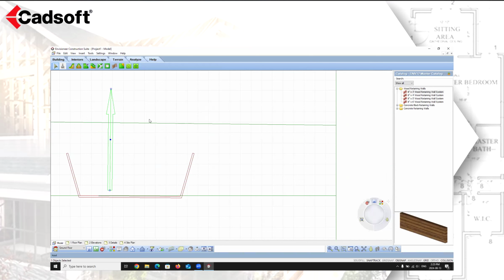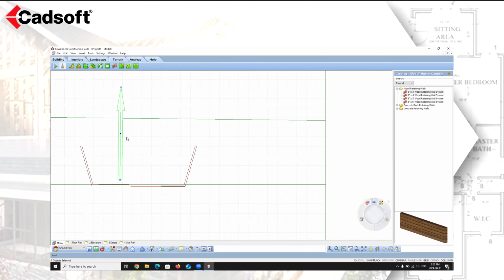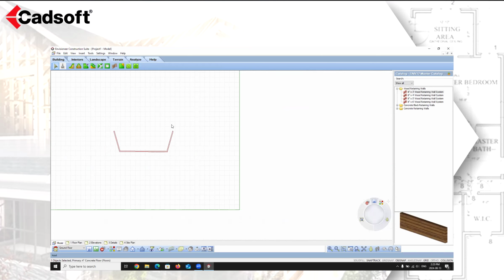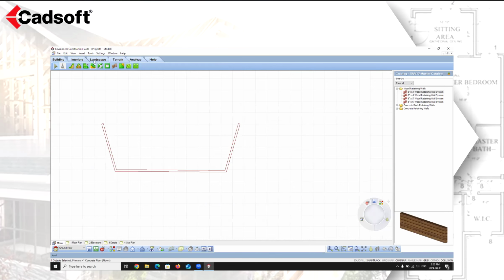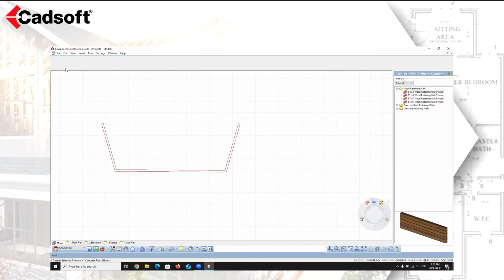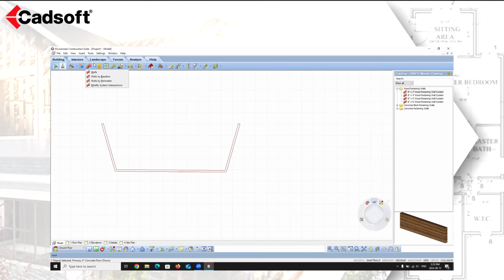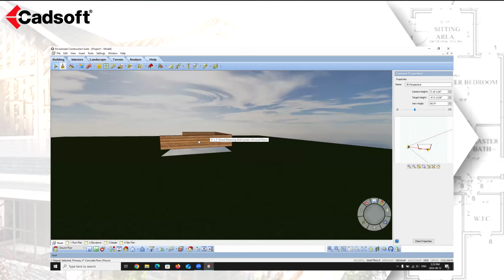And with my terrain, I'm just going to get rid of the terrain for just a second. And I'm going to go back up and underneath my walls option, it's under floors. We're going to do a room division. We're going to be able to add in a room division line. What this will do is cut the terrain out from that area.